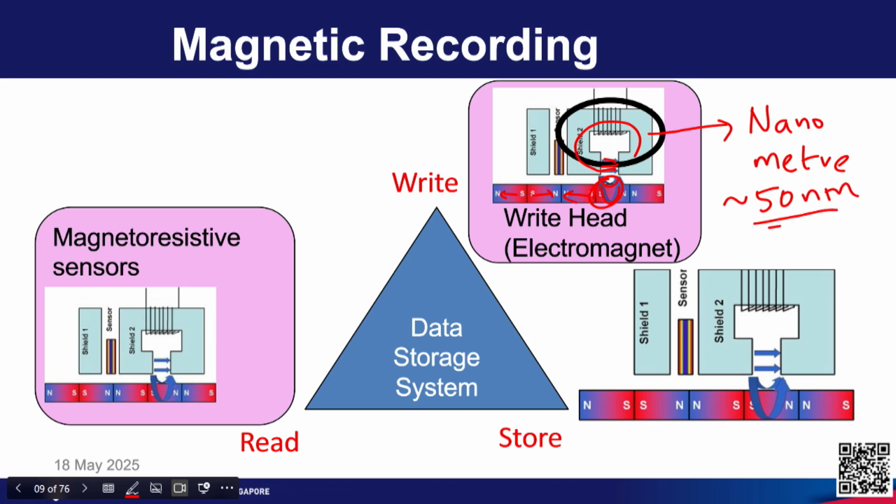So, we are talking about tiny electromagnetic heads to write information in hard disk drive. And for reading, we are going to look at the magnetic flux that comes out of the hard disk drive. Okay. So, we have written some information. We have magnetized the material, it's in certain direction, they produce magnetic flux. So, we sense this magnetic flux as a way of reading information.